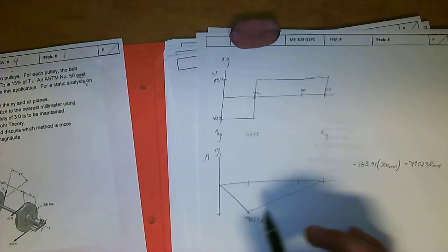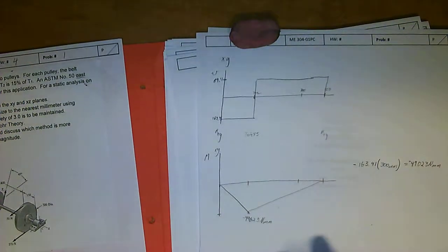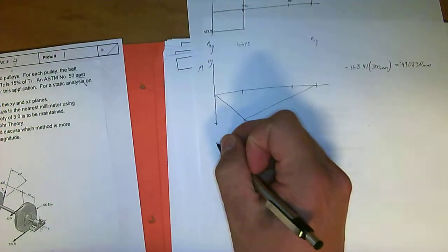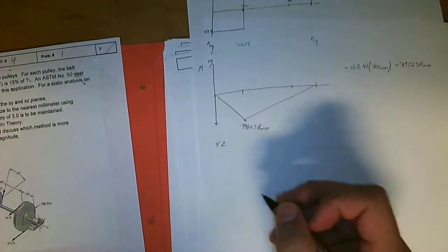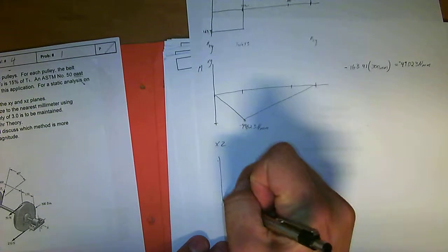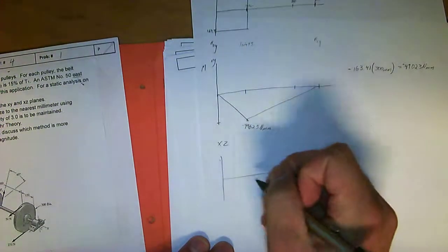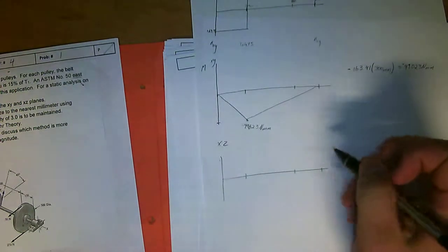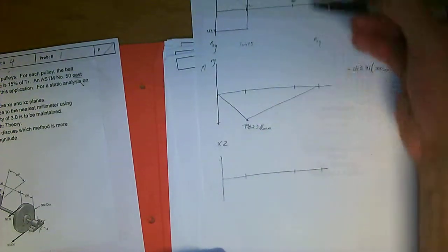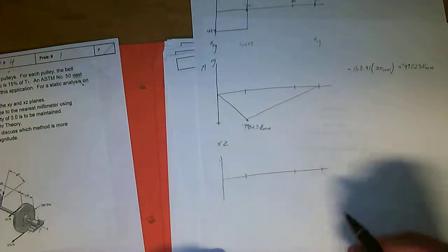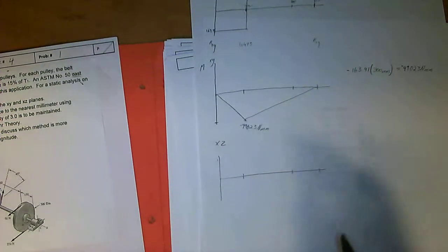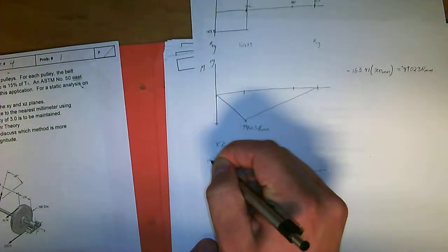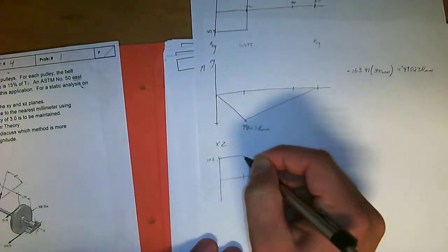Okay, so moving on to the XZ plane. We start out with the basic shear diagram, 300, 400, 150. And you can see how these all line up. This just makes it easier doing the shear and moment diagrams because you know which point it is all the time. So we start out with ROZ, which is 106. That goes over to there. Then we have the negative T cosine 45, which takes that down to negative